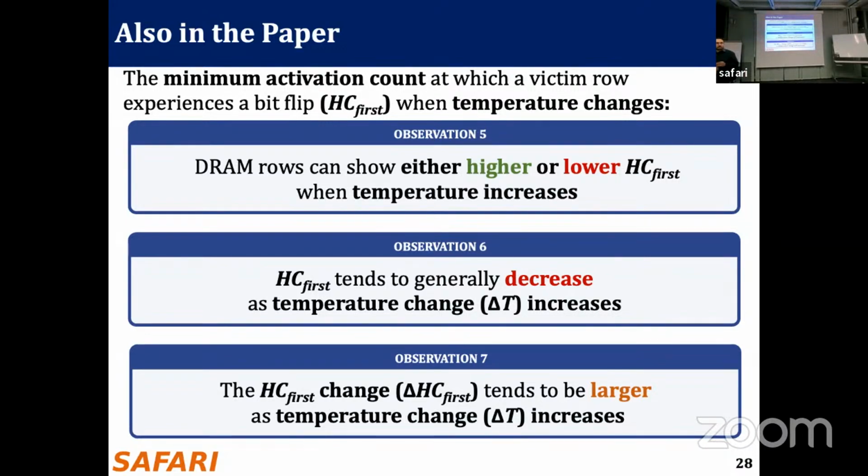Ah, I see. The original RowHammer paper showed that also. That's true, yes. But here, the temperature dependence is not strong at all. It's very weak, I would say. There's some dependence clearly. But with retention, you can easily say that as you increase temperature by, let's say, 10 degrees Celsius, you double the retention errors. I think that was the formula that we showed in our ISCA 2013 paper. Whereas here, you cannot say anything like that. It's not really that straightforward here. Here, it's very much dependent on the cell.